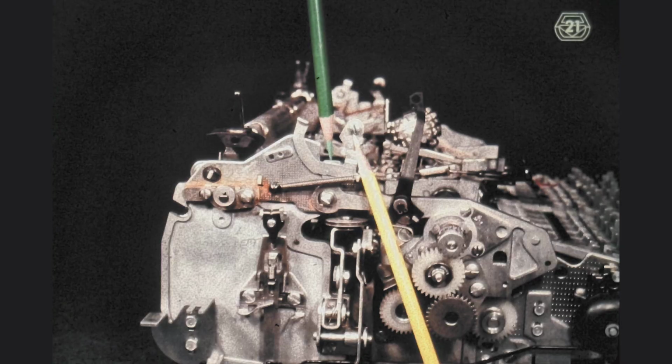Whenever we change the vertical position of the platen, we need to remember that the platen is held down by the clamp indicated by the yellow pencil. Adjusting only the height of the bracket indicated by the green pencil will not suffice, because the hold-down clamp has to hold the platen against the bracket, since the feed rolls would otherwise continue to hold it up. By the same token, we cannot raise the platen without first getting the hold-down clamp out of the way.